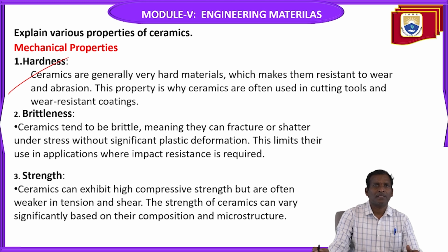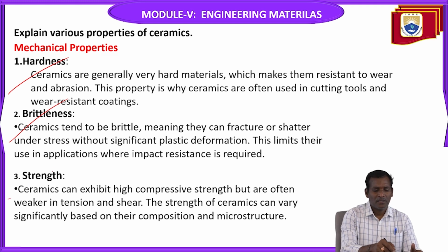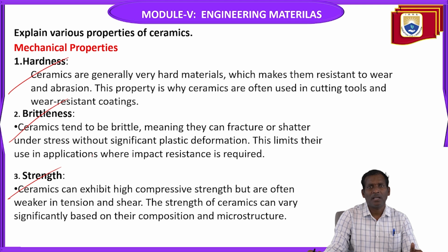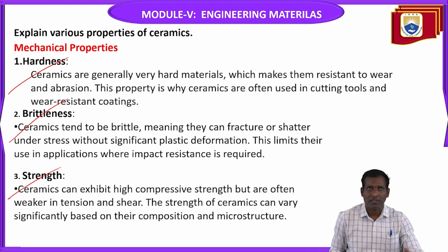And similarly, brittleness. So ceramics tend to be brittle, meaning they can fracture or shatter under stress without significant plastic deformation. This limits their use in applications where impact resistance is required. Strength. Ceramics can exhibit high compressive strength but are often weaker in tension and shear. The strength of ceramics can vary significantly based on their composition and microstructure.